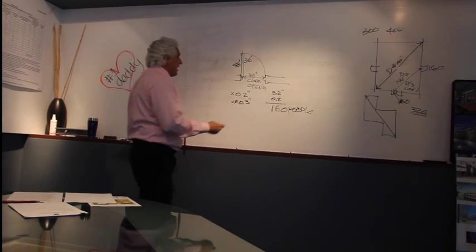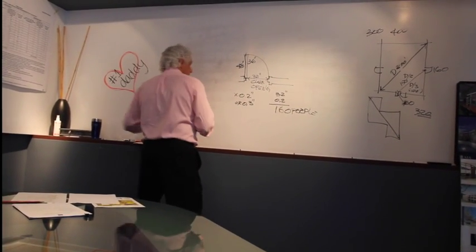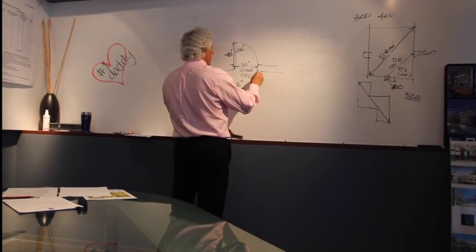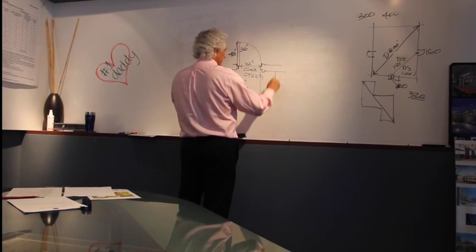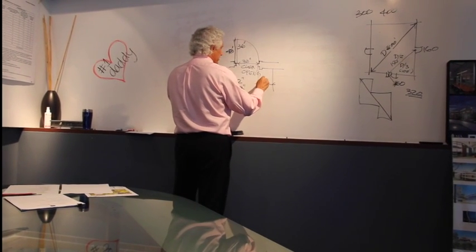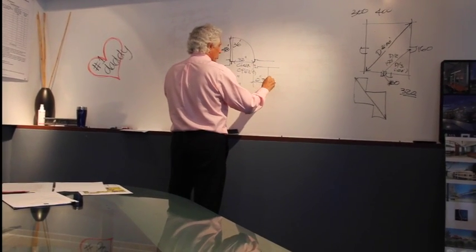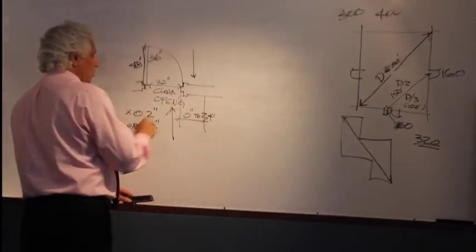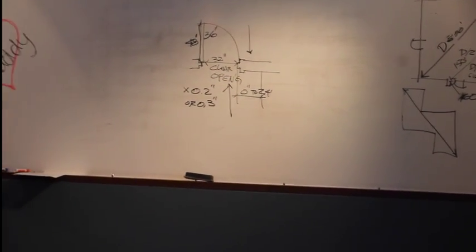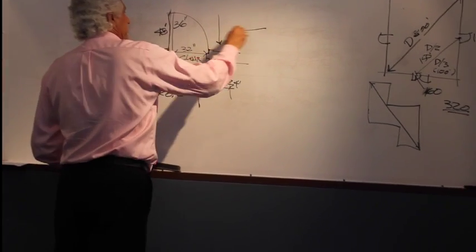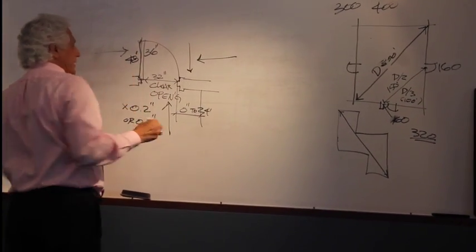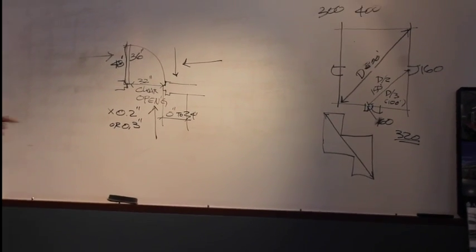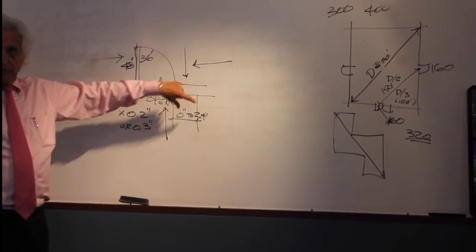And depending on the approach of the door, you're going to be required to have what's called a latch side clearance. How many inches is between 0 to 24 inches from the latch side, whether it be from the approach side or on this other side. And it depends on if you're coming in this direction or this direction. There's actually a chart in the code that you have to examine and determine which way is your approach, to determine how much of a latch side clearance you need.